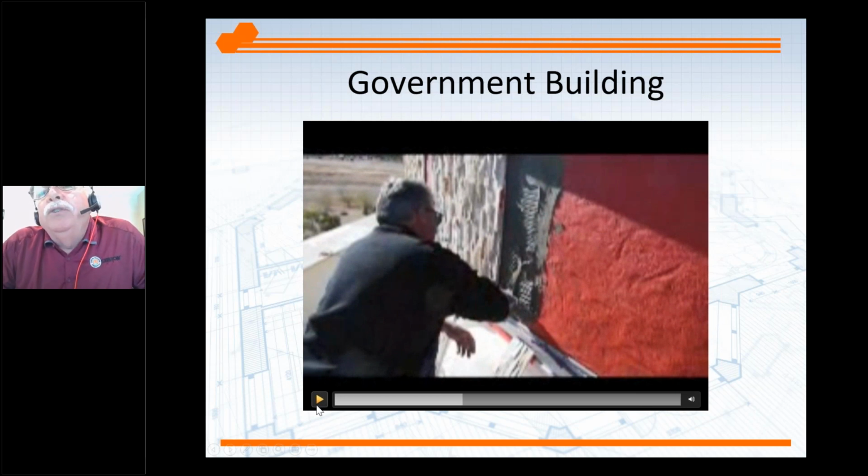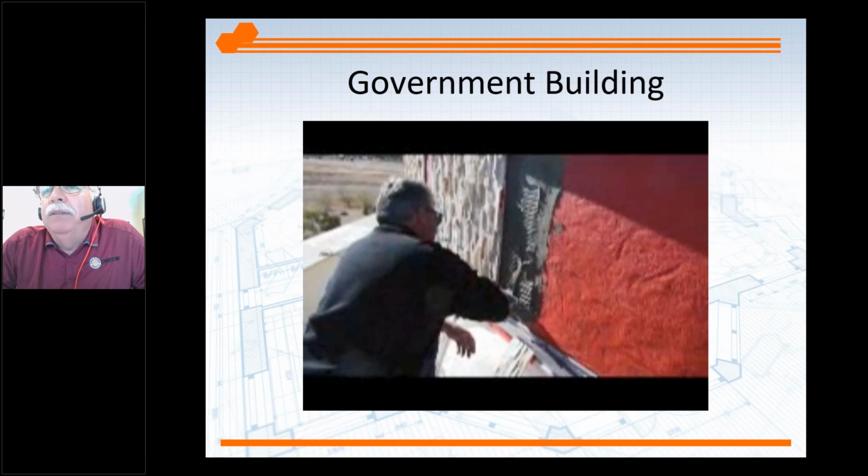So here he's using the flat side of the trowel, pushing it into the substrate. This mechanically locks it in, the flat troweling, back buttering. He's coming back with the notched trowel. This gives it a consistent thickness. All cements, even thin set mortars, have some small shrinkage, so we're trying to get consistent shrinkage out of that, consistent thickness of this. Generally, I would recommend going across.